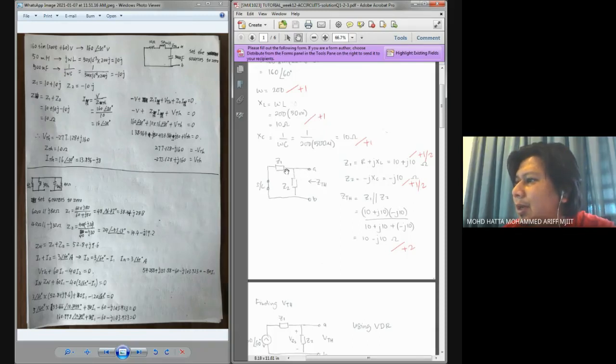And these two elements, if this is considered as short circuit, oh, before that, we need to set all sources to 0. Since in order for us to calculate ZTH, we need to make all sources equal to 0. In this question, we have a voltage source over here, which means that the voltage source should be treated as a short circuit. And Wang also did that.